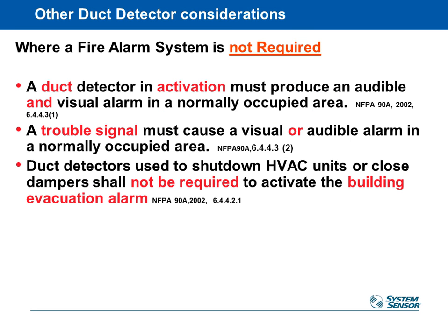So if you have a system that's following NFPA where no fire alarm system is required, meaning you don't have all the sensors up in the ceiling tied together with the hand pull switches and all that, because it's just a little, say, 2,000 square foot doctor's office, you don't have that fire alarm system. You still do have to put the duct smoke detector in.